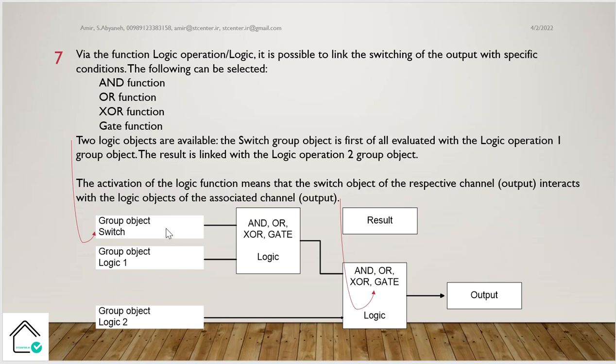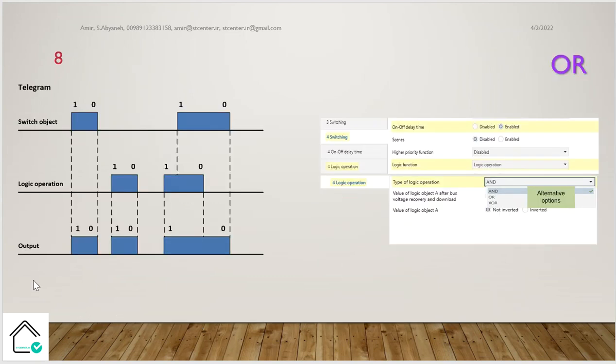But when we say this, it means we should do some parameter setting and then have the group address for the two inputs, and then have the group address for the output, and then have the group address for comparing with the second logic, and have the group address for the outputs. Okay, so in KNX we use the parameter and group address to define the logic in ETS.